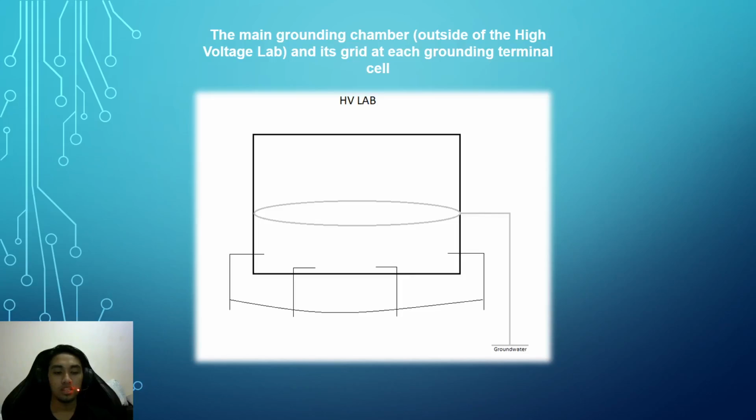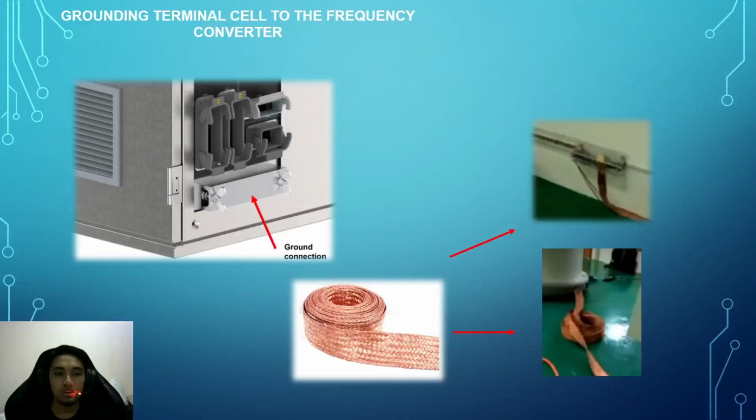Next, we can achieve a value below 1 ohm by using grounding enhancement material, which is GEM. Last but not least, we cannot use any chemical grounding because we need a proper grounding chamber in order to get a grounding lifetime of around 2 or 3 years.